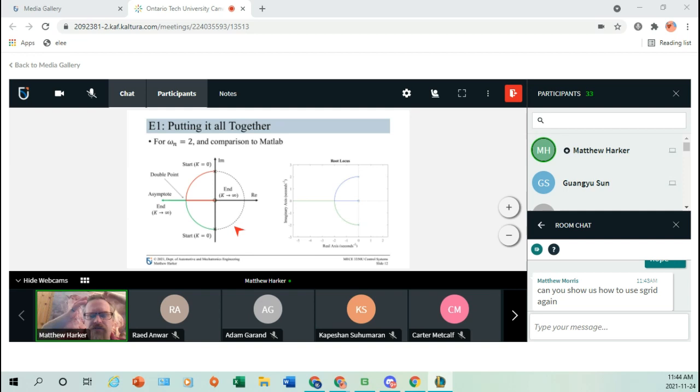So that gives you a physical parameter that you can vary, which would increase the diameter of this circle. And then the damping ends up being an angle on the unit circle as well, as long as we're below critical damping, which is usually what you'll want to make the system as fast as possible. If you go beyond critical damping, you're slowing the system more than it needs to be.